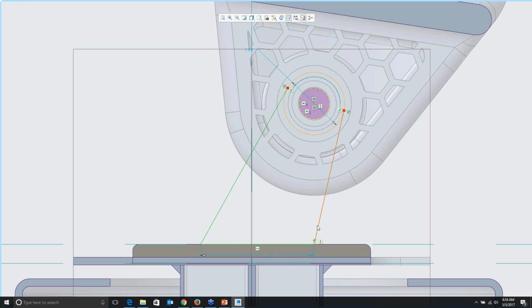And now you'll notice, I'll point this out again. What I did over here was putting my mouse at the midpoint as a reference and then just moving it all the way down to where I start to sketch down here. Ordinarily, that is something you would have had to do with a center line, right? In prior versions of Creo, you would have to draw a center line vertically down from here before you could start picking the midpoint where they meet, and then going off on that.